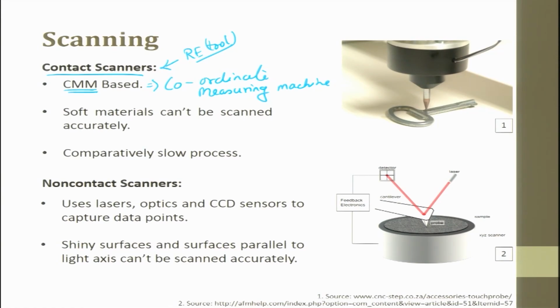The probe in turn is attached to a spindle. There, the moment it touches a part, it can be conducting, non-conducting, whatever it is. Moment you touch the part, this probe has a contact which is there in the spindle, it breaks the contact and immediately XYZ data points are recorded. So, that is how a CMM works.